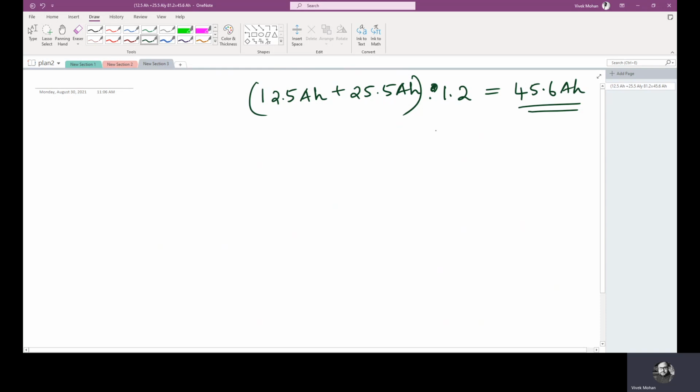Because the energy a PV module delivers depends on several factors based on the weather conditions of that location, then seasonal changes, and it depends on the installation of the modules also. The modules can be installed with a tilt angle, or it can be horizontal. So in different angles, it will give different performances. So it is also important to know whether a PV system is expected to be used throughout the year or only around a certain period of a year.